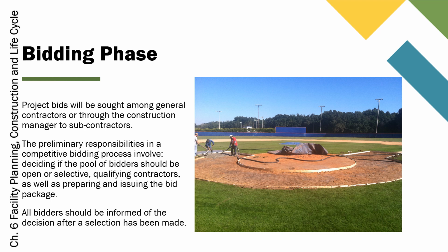Is it going to be open bidding versus selective bidding? Open bidding allows all interested contractors to submit bids for the project, promoting broad competition. Selective bidding is more restrictive and involves pre-qualifying contractors to ensure that they have the appropriate experience, expertise, and financial stability to handle the project.